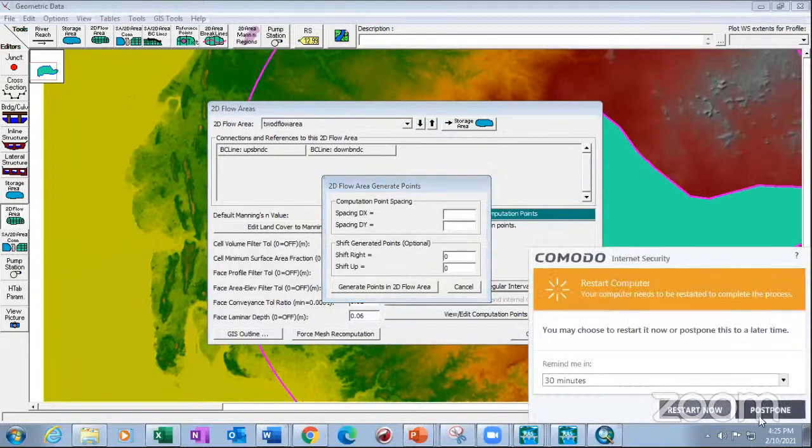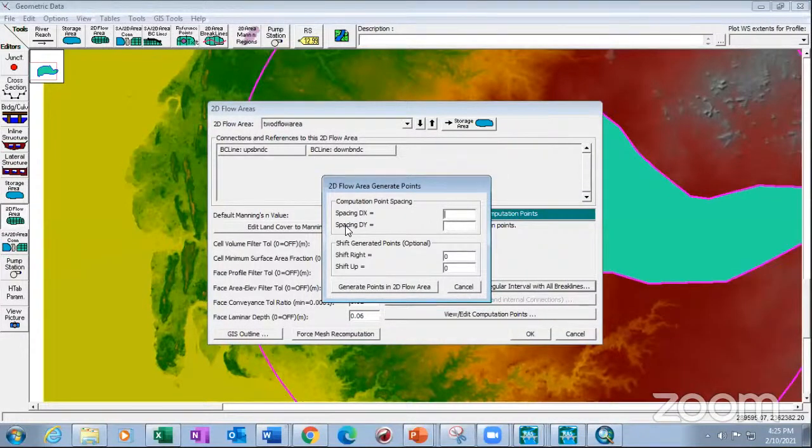Courant number means the time step, with velocity times delta t upon delta x, should be less than or equal to 1. That's how you have to satisfy the Courant number. But the problem is that trying to satisfy the Courant number may result in so many grids also. So in that case you have to do some trial and error and come to the optimal size of the mesh.